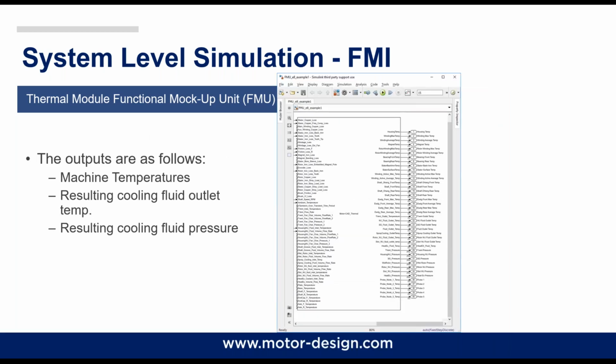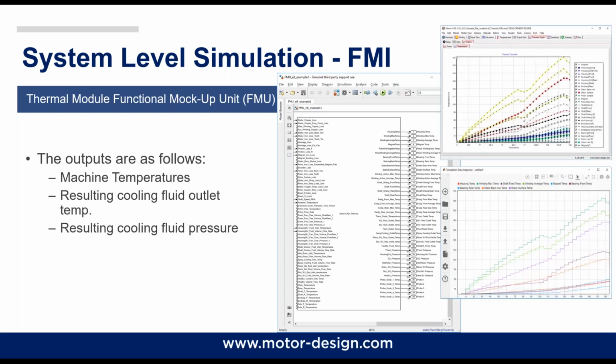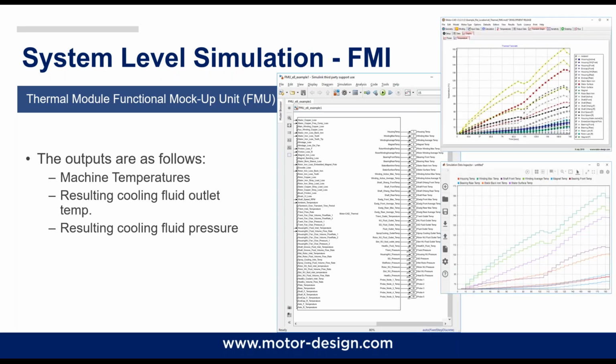The outputs of the thermal one can be divided in machine temperatures, where any node within the thermal network has to be included as a probe. The resulting cooling fluid temperature and pressure based upon the coolant input parameters, machine geometry, and power dissipation into the cooling fluid. The results of the transient thermal simulation are presented, where at the top we can spot the MotorCAD thermal transient result, and at the bottom the one from the FMUs.